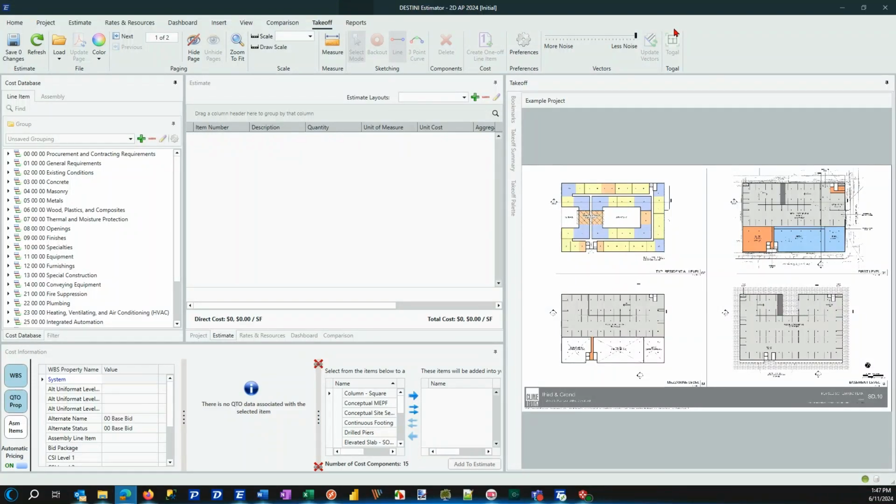Well, now that we have a drawing set, the next thing, and this is really the responsibility of either the team lead or the person that is responsible for the drawing sheet, they have to set the scale in order to activate the draw commands. And so I'm going to go ahead and set the scale to 1 to 30, and now everyone else can use this same drawing and, of course, work with their content.